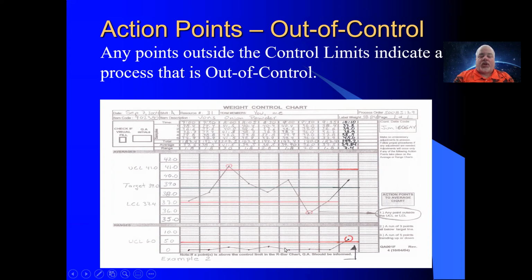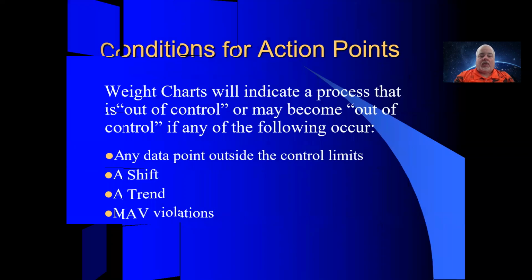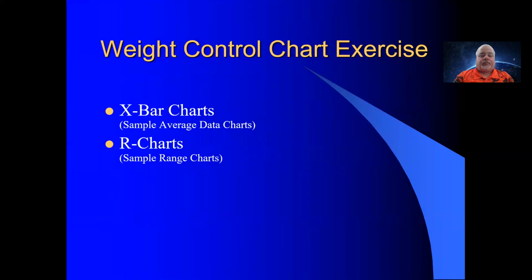And there's an upper control limit. If you have any more than 5-gram difference between the high and the low, that's a problem. So that's what the X bar chart or the mean chart and the R chart or the range chart at the bottom, that's what they look like. So let's go back.